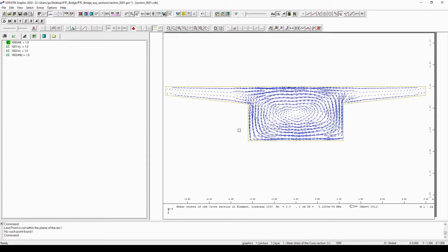And if you try to imagine, our cut V1 is somewhere here, so it is very important that at the beginning of the cut the shear stress is acting in the vertical direction downwards, whereas in the second part of the shear cut, the shear stress is acting upwards. As you can see, the sign of the shear stress from the torsional bending moment can increase or decrease the effect from the vertical shear force.